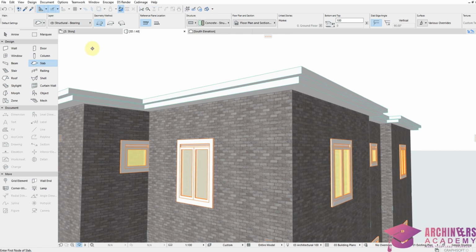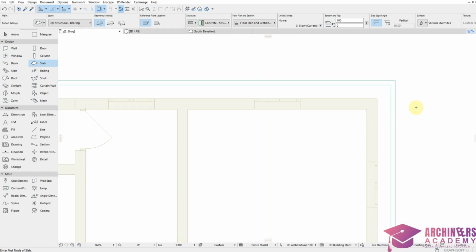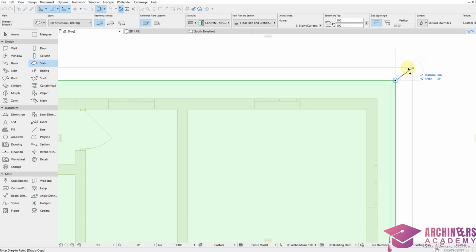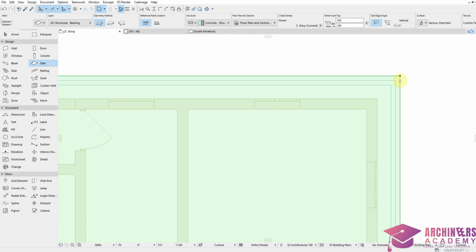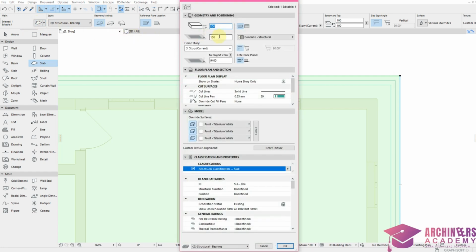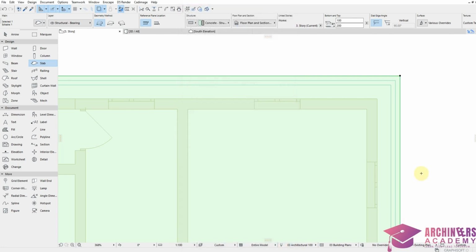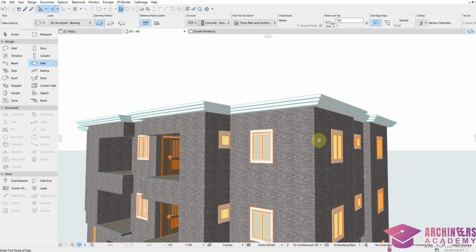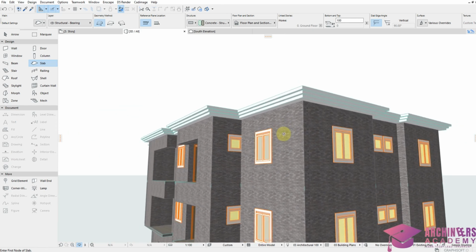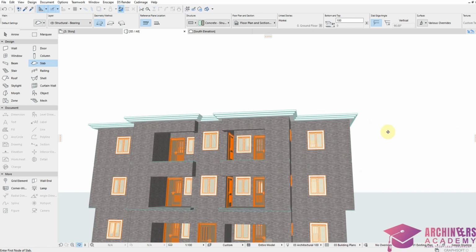So we'll do it again. Let's do like 3 steps. So remember, I pick the one I want to offset next. Ctrl Shift D, which is drag a copy, place it back, offset it again by 100. Your offset distance is your choice. So just follow the same steps. Then now we'll add extra 100. This is now 200. So we have done this successfully. So you can now see the fascia.